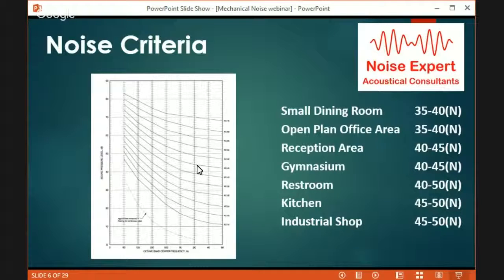The noise criteria is a little different. They have these curves, and this is a small figure here, but the octave levels are plotted, and you just pull off the highest curve that's been touched. So they're not going to track equally, dBA and NC, but there are some published guides that give you more or less a correlation between the two. Because you could have just one spike in one frequency, everything else being low, and it's touching this curve, or you could have everything up against this curve, and the A-weighted and NC would be off a little bit.